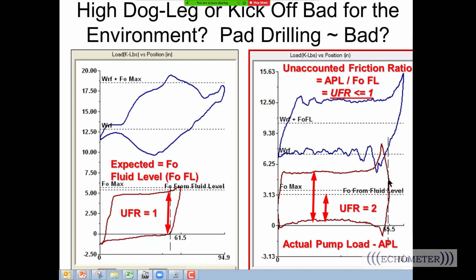That meant the wave equation already somewhat models, or has been modeling, coupling-on-tubing friction, because that's a friction, but it's not really a function of velocity. That's just a drag coefficient friction. So this is really complicated, and that's kind of why we're working on this project at ALRDC to build this downhole load cell, because we want to be able to measure the mechanical friction forces and then be able to calculate them.